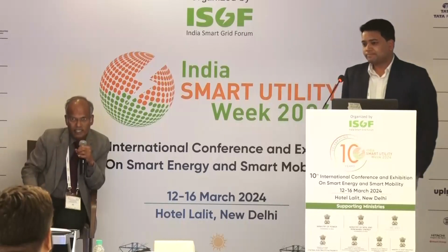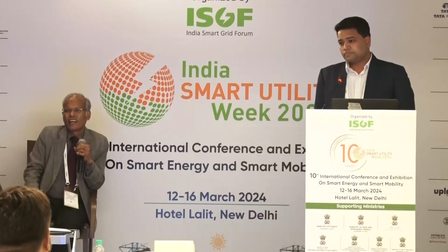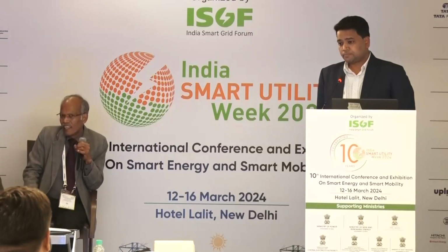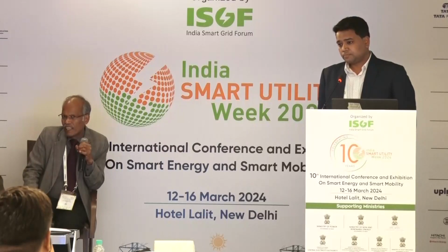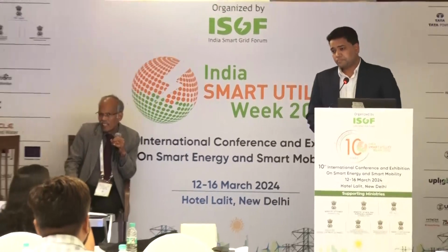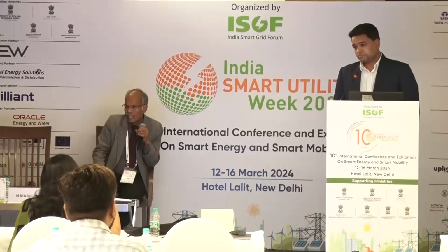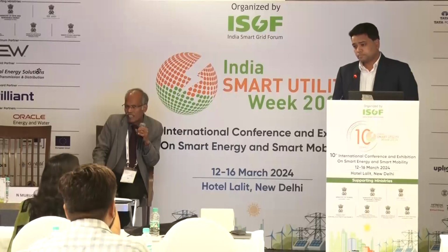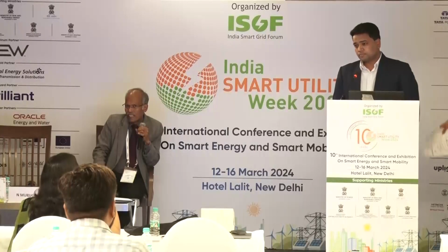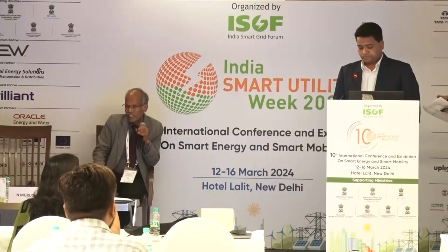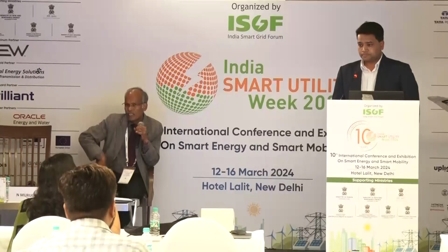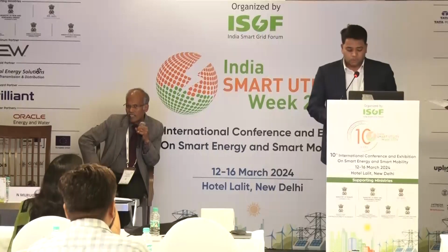Yeah, so we all know the importance of SF6 as far as switchgear is concerned, and the voltage levels beyond which we normally opt for SF6. The question is inquisitive, in terms of understanding the property of SF6, which is an electronegative gas. Yes. And that's why it has affinity towards electrons. It helps in quenching of the arc which happens in the switchgear. Yes. That's why I just want to know from you, for the alternative gas, which is absolutely eco-friendly, what is your observation related to its arc quenching property?